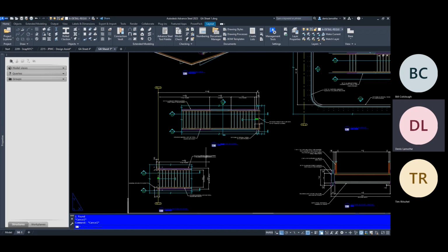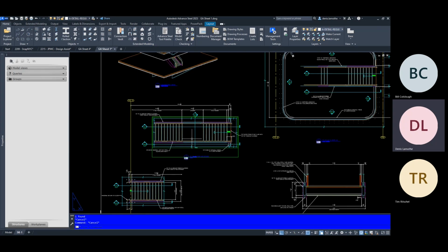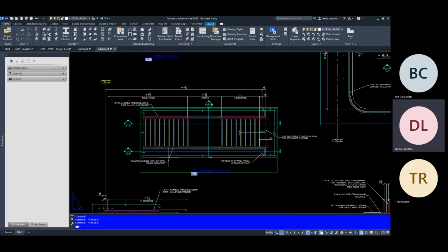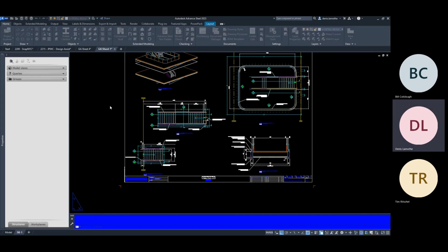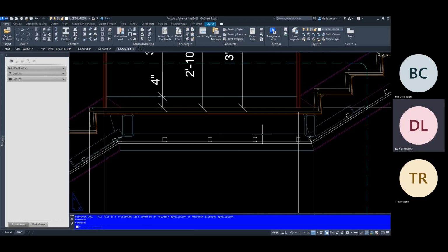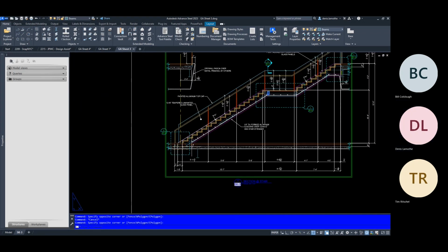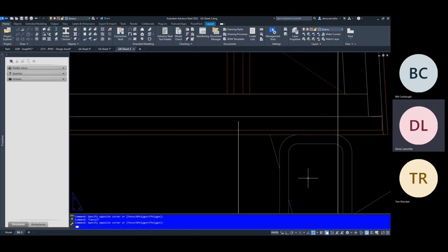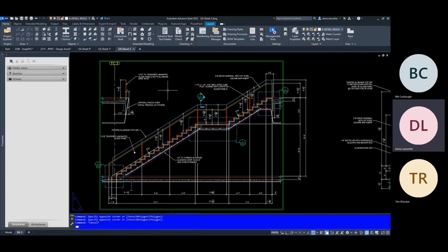And then if I need to show something a little bit more in terms of the structural components of the stair, then I either do a separate drawing, like if there's some really special situation, I might do a separate plan drawing of just the structural steel, or rely on seeing that in the section views for the stair, and then hope that the section views convey all the internal structural members that are in there. Not that there's a lot in this particular example that I'm showing, but yeah, Advanced Steel limits us a little bit in terms of our presentation, graphically speaking, anyways.